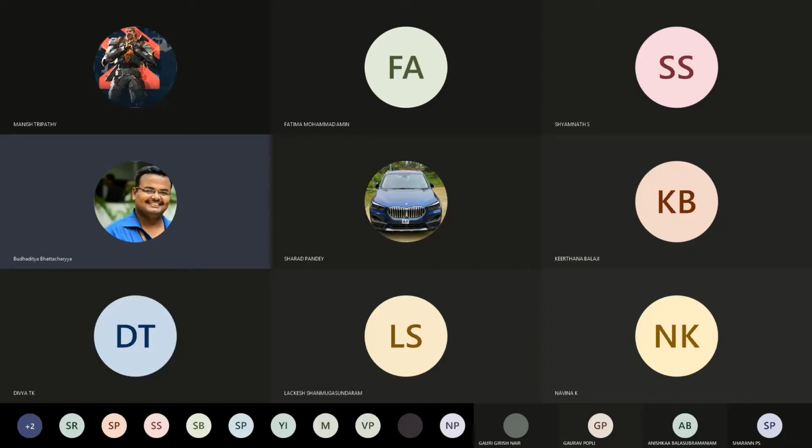So before we start anything, let me just recap what we had done in last day's class. If you remember, we did a particular modulation scheme, which is basically a refinement to modulation, and that was DSB-SC, double sideband suppressed carrier, in which the principle was to minimize the carrier, to nullify the carrier by some means, since the carrier doesn't contain any information.